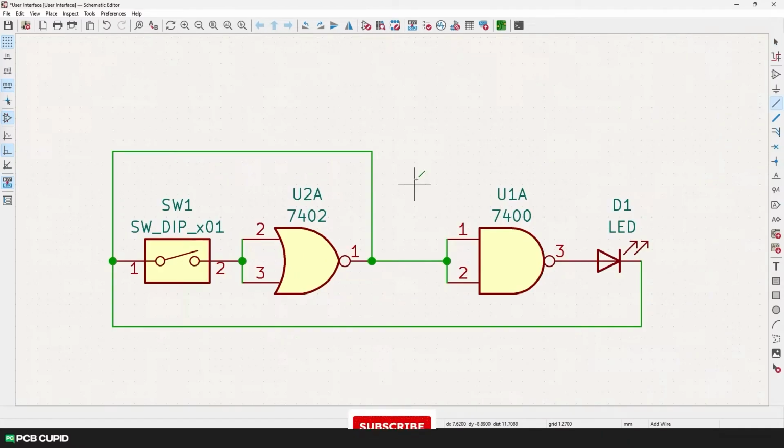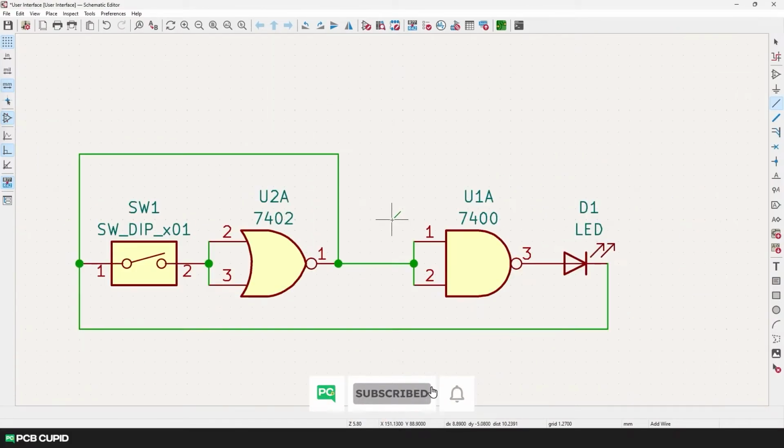And now if I zoom in and zoom out, you can see small points where our cursor snaps onto. These are called grid points, which will be of great help when connecting two components together, so we don't have to fiddle around to connect them properly. And you can see the distance between them over here. And finally, the mm represents the millimeter. That means all the values that are shown here are in millimeters.